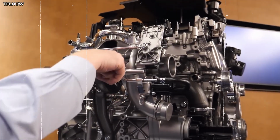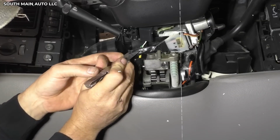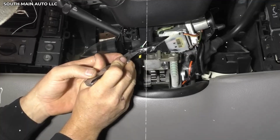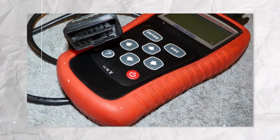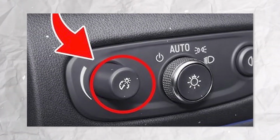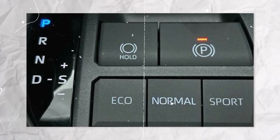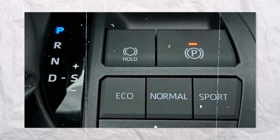Method 3: ForScan permanent modification. For owners who want permanent control over throttle response without constantly doing resets, the ForScan method lets you modify the actual calibration files in your Ford's computer. This requires a laptop, a $50 OBD adapter cable, and the free ForScan software, but it gives you complete control over dozens of hidden settings, including throttle sensitivity.